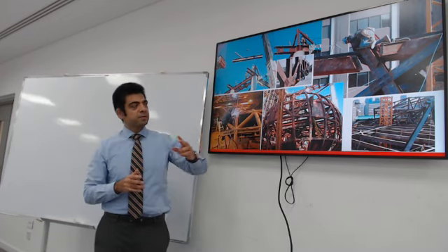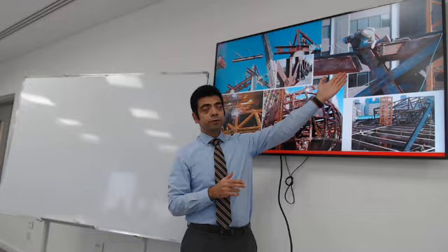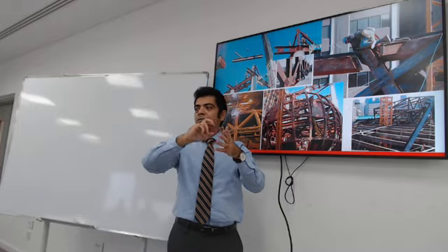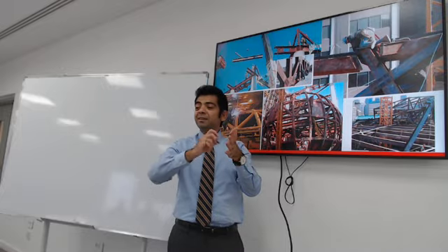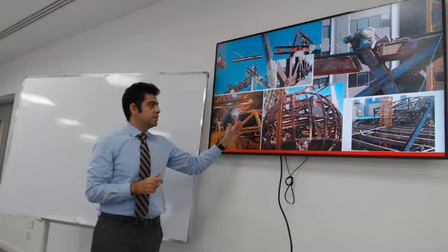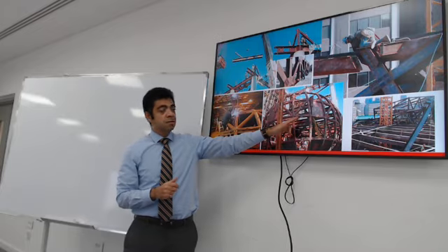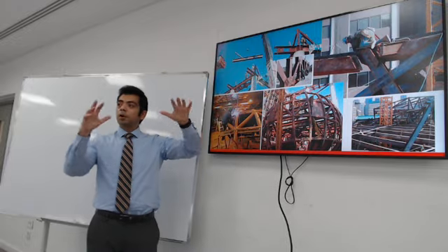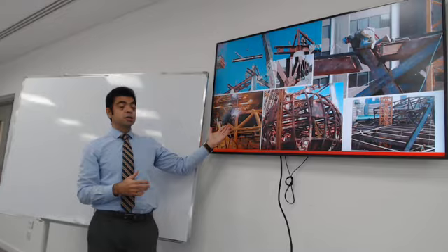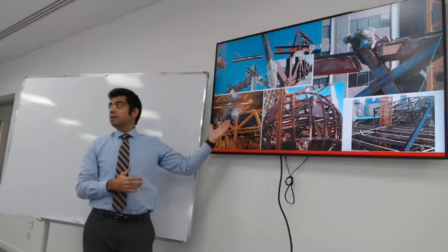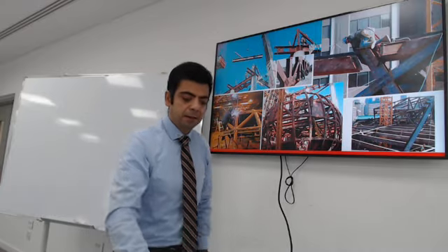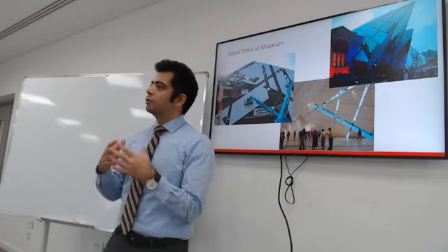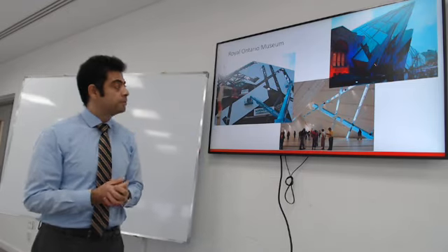I have two examples here. This is an example of a bolted connection. You need the crane to line them up. The worker on site will install the bolts and tighten them. This is an example of a welded connection. This part is bolted. The rest of the frame is welded. It's shipped on site welded, so it's done in the shop. You see how this is welded in the shop, and then you send it on site, and very rapidly, the building starts taking its shape.